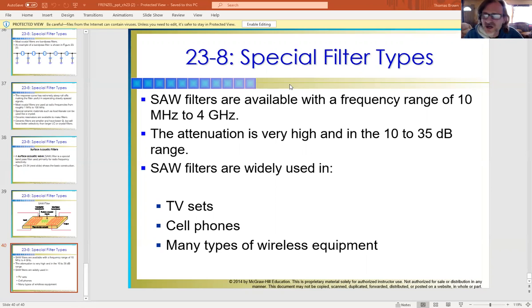And you'll find that these are what they consider active components. So in the case of a chip, you actually apply a DC power level to it. In the case of TTL, it's a +5, and you would incorporate a ground to it. And then it's an active piece that you can subject to different signals to get your desired output.